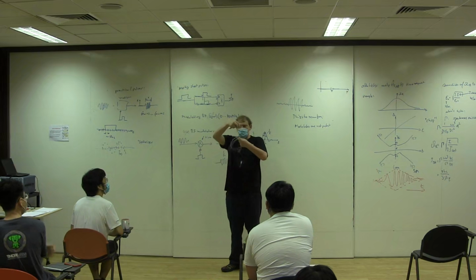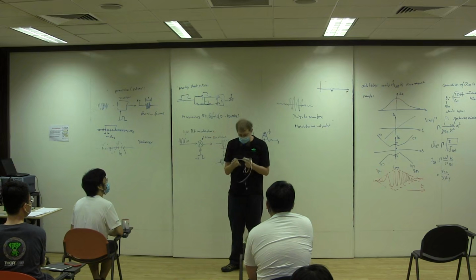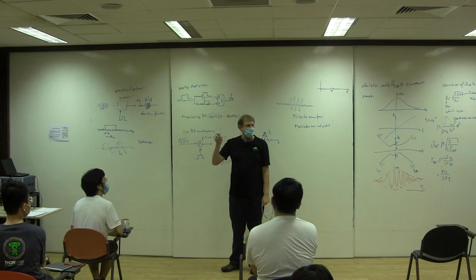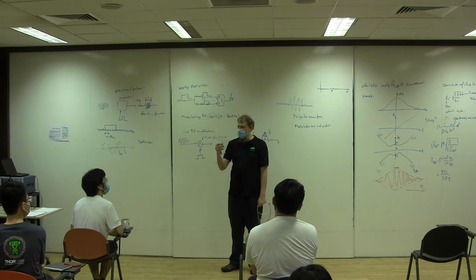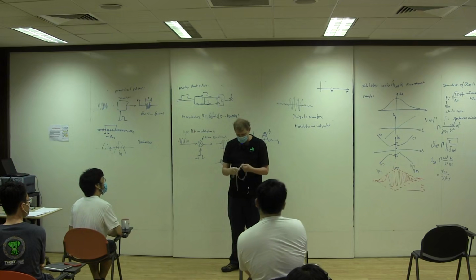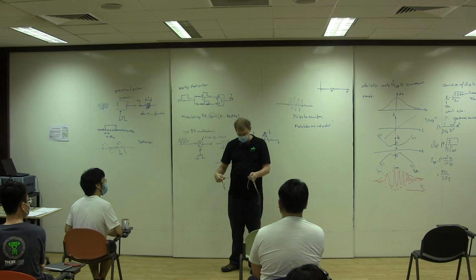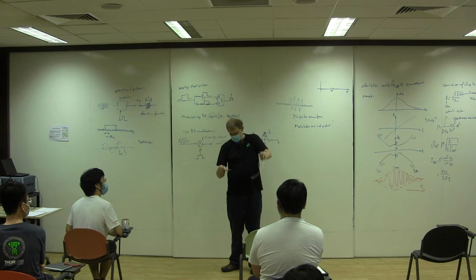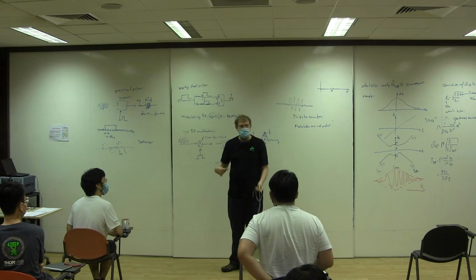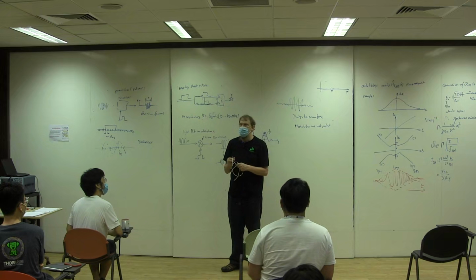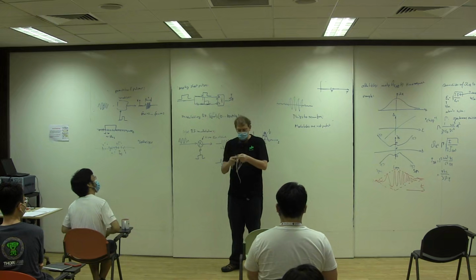This is a short coaxial cable. It acts like a waveguide, and it is like 20 centimeters long. It takes about 1 nanosecond for a signal to travel through this cable. The speed of light in this thing is 2/3 of the speed of light, because I think it's a polyethylene insulator. So 20 centimeters correspond to a nanosecond. This is a cable, well, I don't know how long that is. Looks like half a meter, something like that. It's maybe 2.5 nanoseconds or something like that.